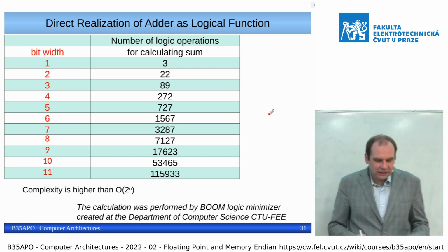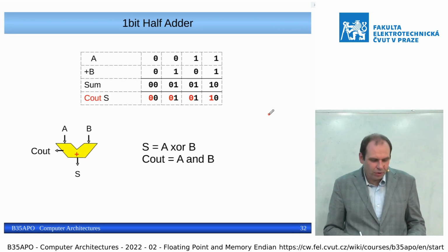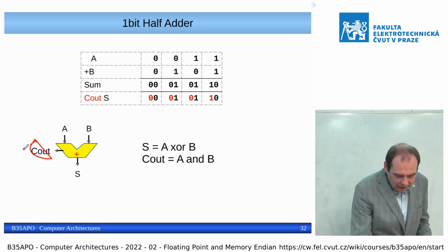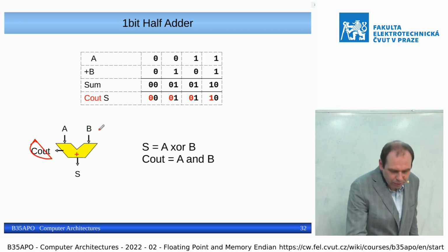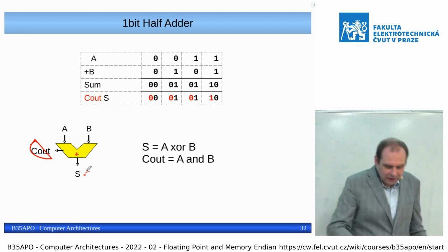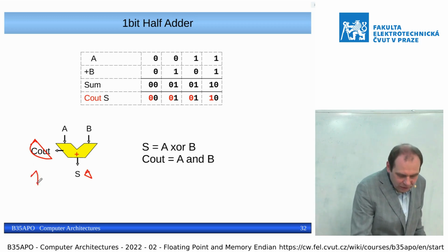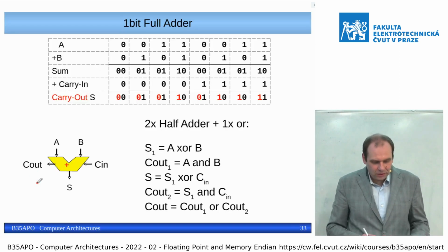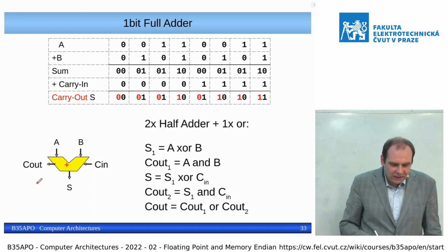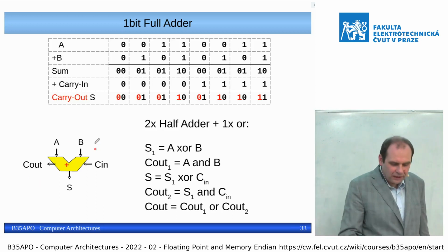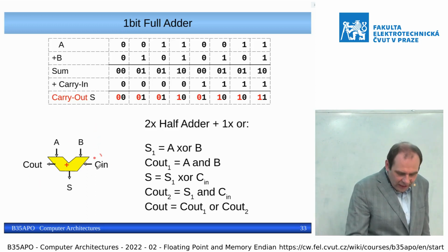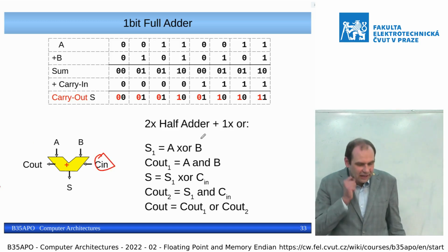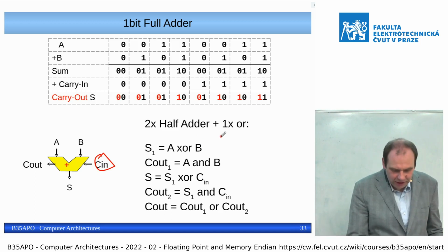We have seen that the adders are quite a big problem, that we can have a simple adder, but it provides a carry out, because if both 1-bit inputs are at 1, the result is 0, but we need to put somewhere the outgoing bit, so it is a problem. We need a full adder because we usually want to serialize them and build the adder for more than a single bit. There are the logic expressions.